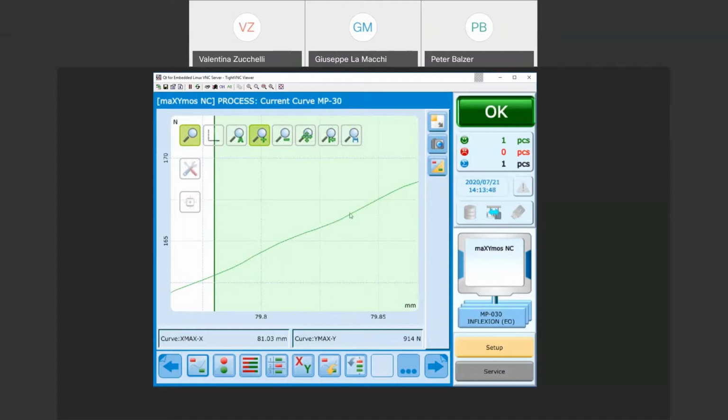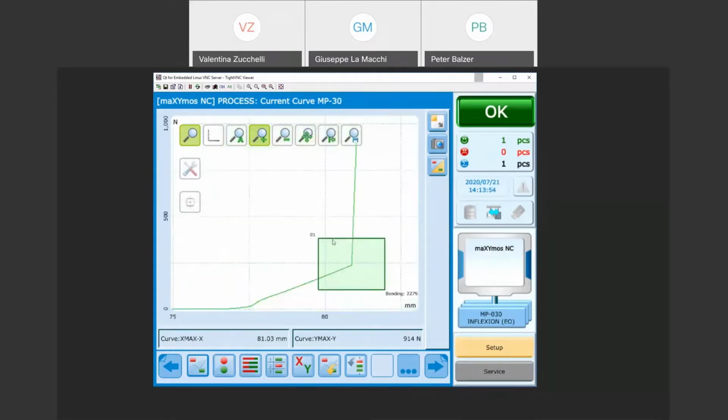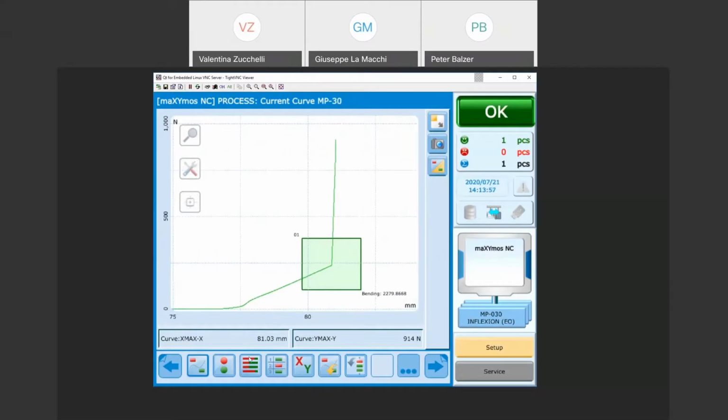And this is normal. That's not a problem. It could be some EMC influence or whatever. But this is really the death for the inflection detection, because you never get your inflection detected right. That's important: a high sampling rate and, of course, a low pass filter. Otherwise, it doesn't work. So that's my experience.